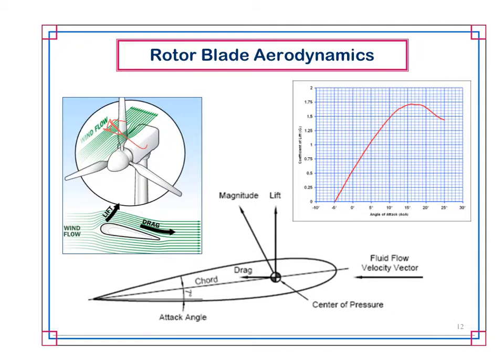if you were to rotate in a counterclockwise direction. This is just some of the terminology you'll see where, again, you do computational fluid dynamics, where you have the wind, and again, you've got a shorter distance going under than over, and that gives you the lift. And then some of the other plots here where you have angle of attack, so you can adjust the amount of lift that the wing or the blade is going to experience by adjusting this angle of attack. You can increase it or decrease it depending on your perspective, and you get a higher coefficient of lift.